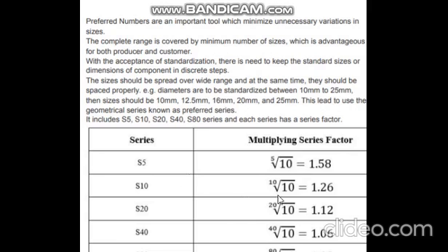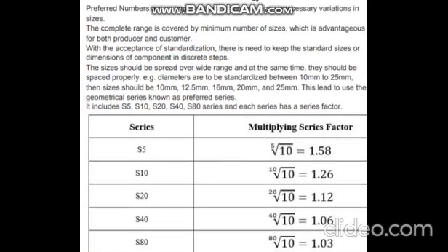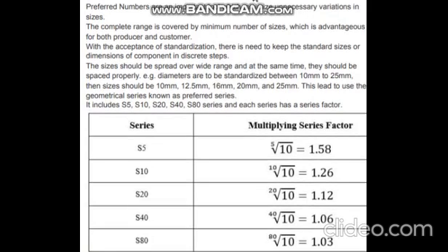If it is the 10th root, then this is the R10 series. The 10th root is 1.26. The 20th root is 1.12. This is the R20 series. The 40th root is 1.06, that is the R40 series, and the 80th root is 1.03, that is the R80 series.